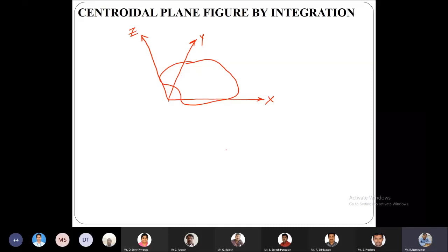So let us assume that this object is having a certain area A, and this particular object is attracted by the force of gravity. We all know that all the gravitational force will be acting towards the center of the earth. But for practical reasons, we will be denoting that all the forces which are acting on it are parallel to one another. To talk in a simple context, here I am discretizing that object into a variety of smaller elements.